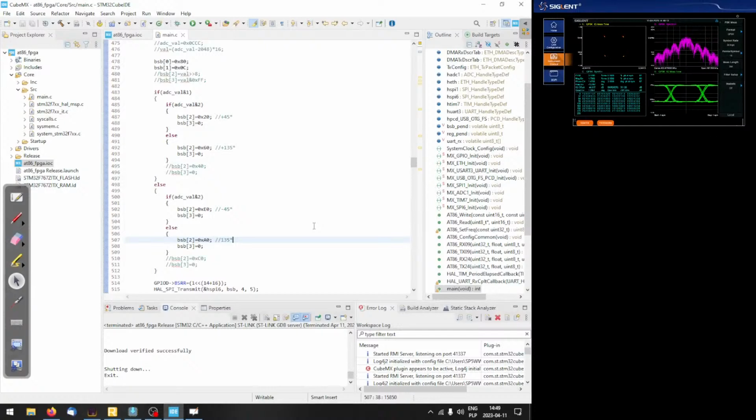All right, so if this works and if BPSK works, oh, it's also important to note that the baseband is a staircase, so it's not filtered. I mean, the baseband is just 4 values, and there are no smooth transitions between all those samples. So we just send the one value, then the other, then the next one, and so on and so forth.